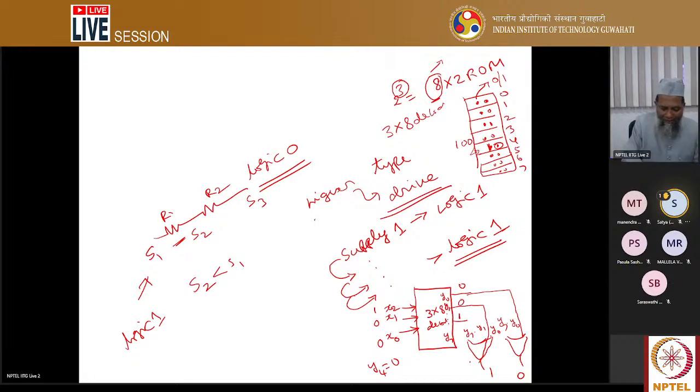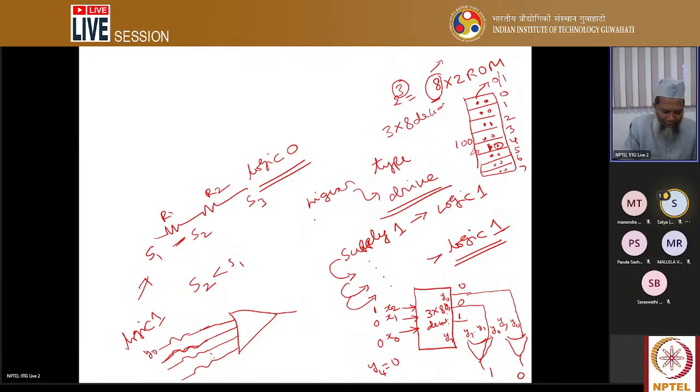So here, if I take this OR gate with 8 inputs, it will be connected through fuses, like the fuses in the electricity department, in our house wiring. If I give 100, out of these 8 outputs Y0 to Y7, only Y4 is equal to 1. Take this as OR gate 1, O1, and this is O2. I want the output of O1 to be 1, so I will keep this Y4 connection intact. I will not break it. The other connections, even if you break them, do not matter.